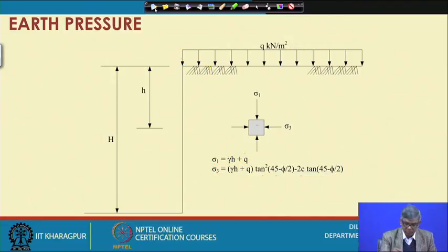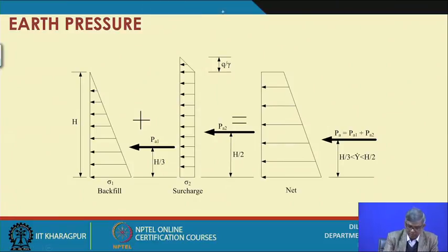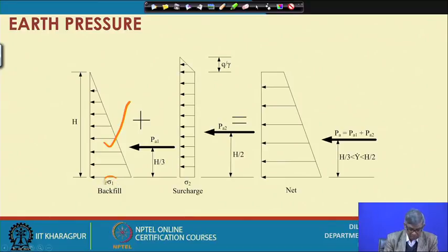So if you accept this philosophy, then I can show you the next slide. You can see corresponding to this, because of the soil pressure from here, this is the diagram. So sigma 1 is gamma into H into Ka, and this is the diagram, as I have assumed the height, because of this height it becomes pressure this much.